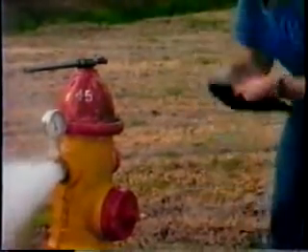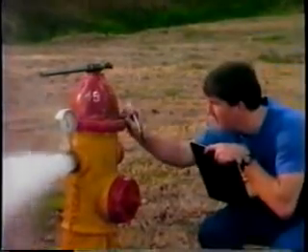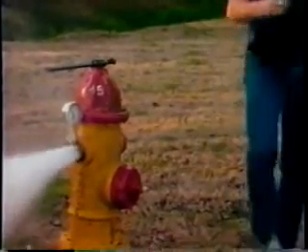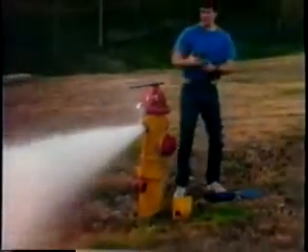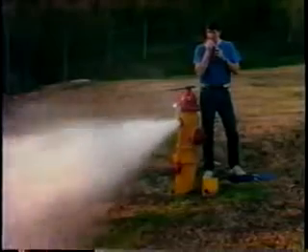Now remember, if several hydrants are involved in a test, the flow at each hydrant is going to change depending on which other hydrants are open. So the individual at the residual hydrant needs to notice, when he has a reading from a particular hydrant, whether this reading corresponds to 1, 2, or more hydrants operating.